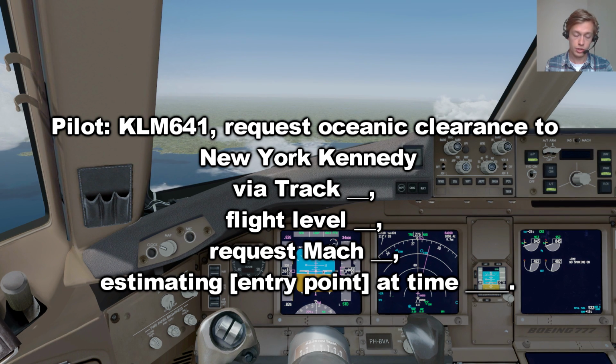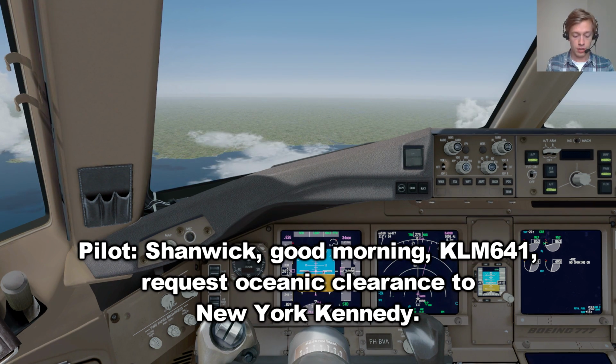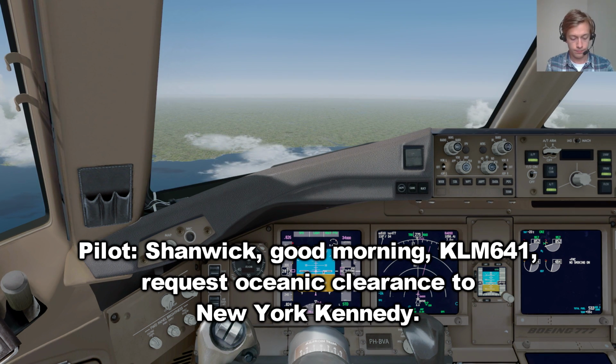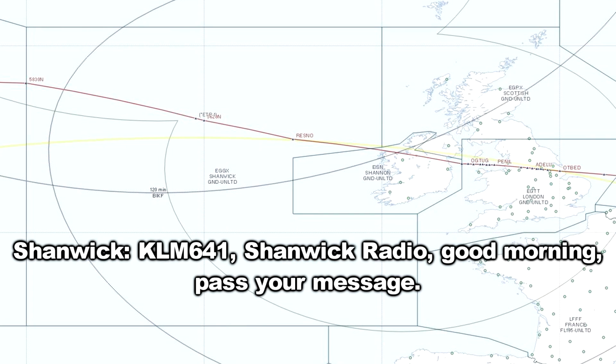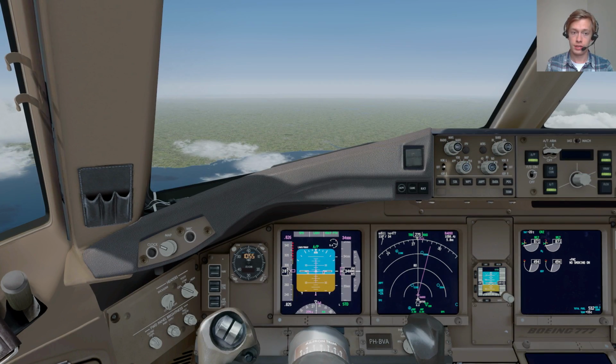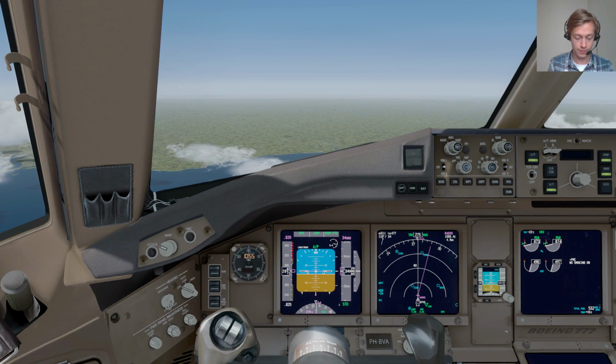Now, I'm just going to show you the exact phraseology right now. So we're now with the Shanwick controller, and I'm going to ask Oceanic clearance. Shanwick, good morning. KLM 641, request Oceanic clearance to New York Kennedy. KLM 641, Shanwick radio, good morning. Pass your message. When the controller says that, you know he's braced for your Oceanic clearance, and then you can continue with your Oceanic request.